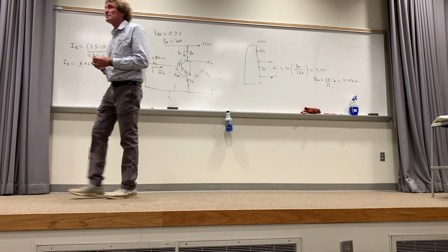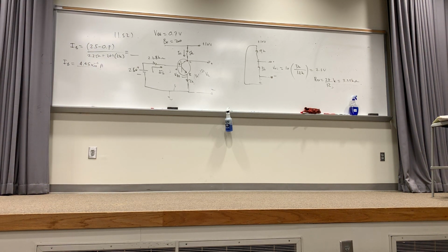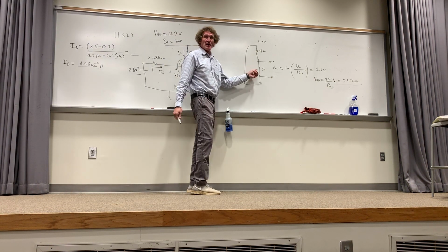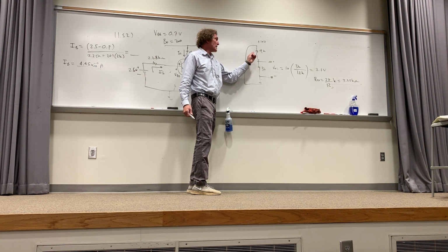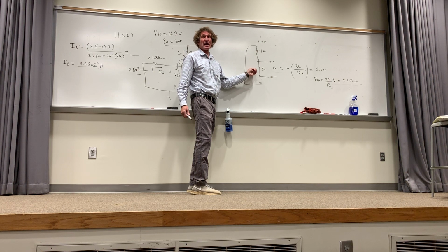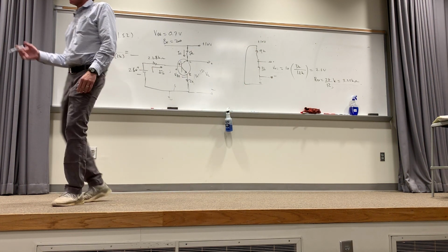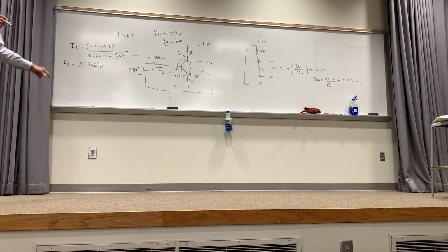For our Thevenin, for that 27K over 12K, should that be 2.5 ohms instead of 2.5K ohms? Well, if you look at that, this is K and this is K, right? So if I take 9K times 3K, that's 27K squared, divided by 9K plus 3K, which is 12K. So K squared over K is just K. All right. Back to this thing, that's IB.